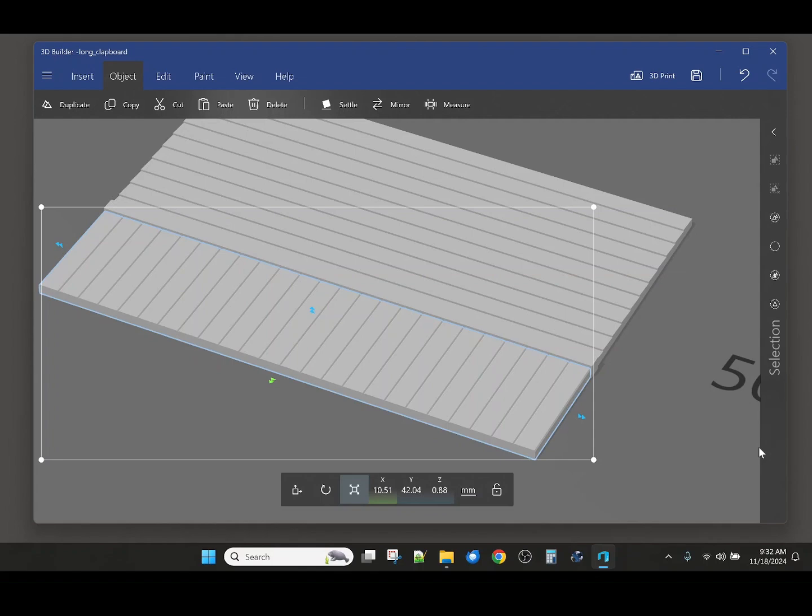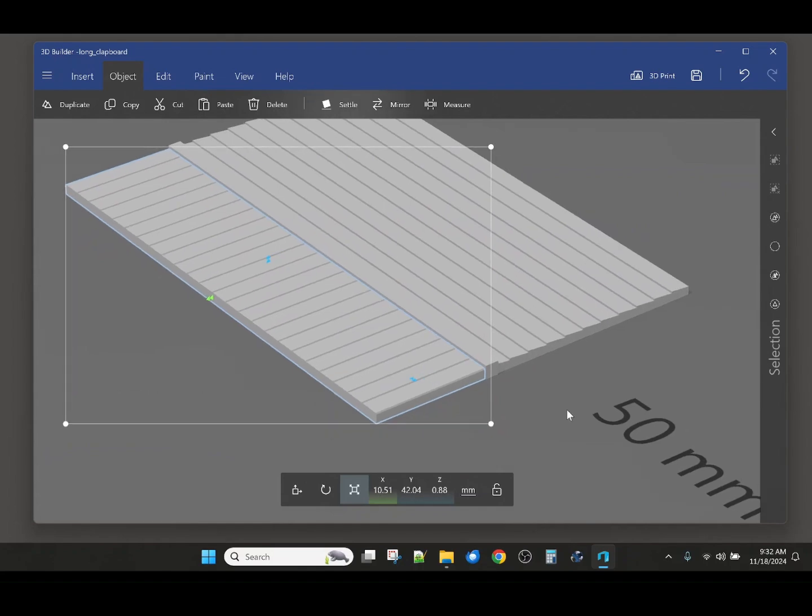You may be asking, why are we using a 4x4 board for trim? The reason is this board serves a functional purpose in the model, and that is to provide a continuous volume between the two wall parts. It is not a safe assumption that butting two parts up to each other will do this. Floating point precision may produce a minuscule gap between the two, which then makes the two parts print separately. Overlapping the trim board over the two parts eliminates any such gap.